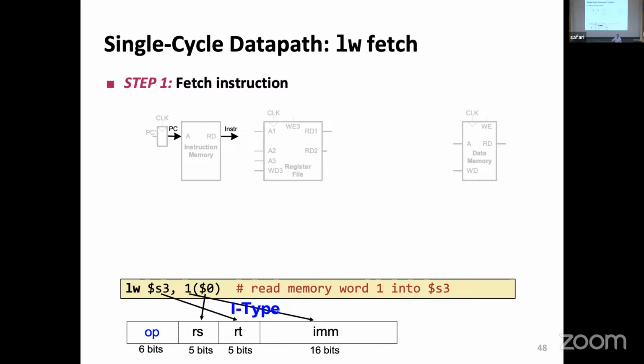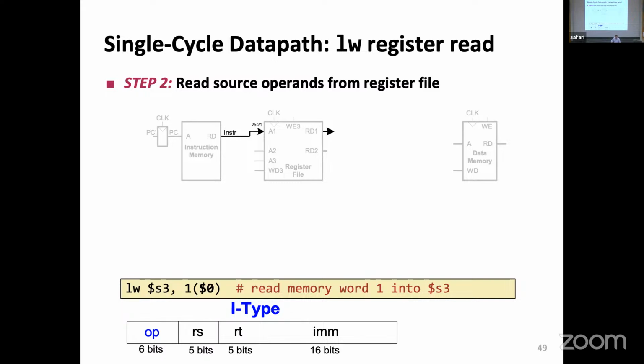So this is what the instruction decoder is able to do. Now, the first part of the operation is trying to figure out what the base address is. We already said that the base address is here, in bits 25 to 21. If you count the bits, you will realize that these bits select the RS, and I'm able to read this thing out from the register file.